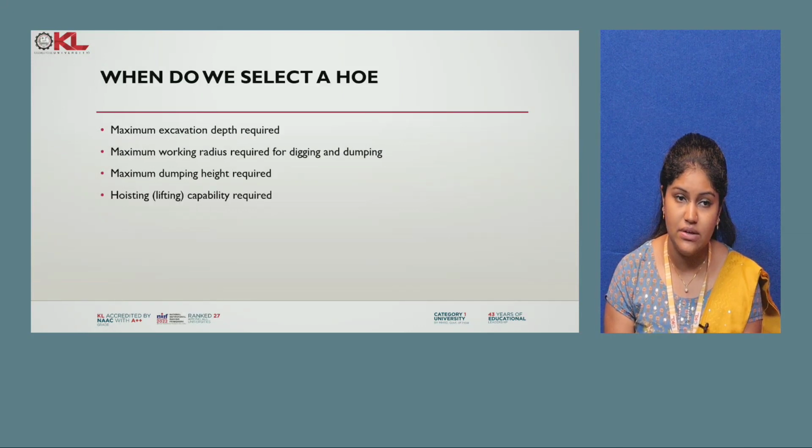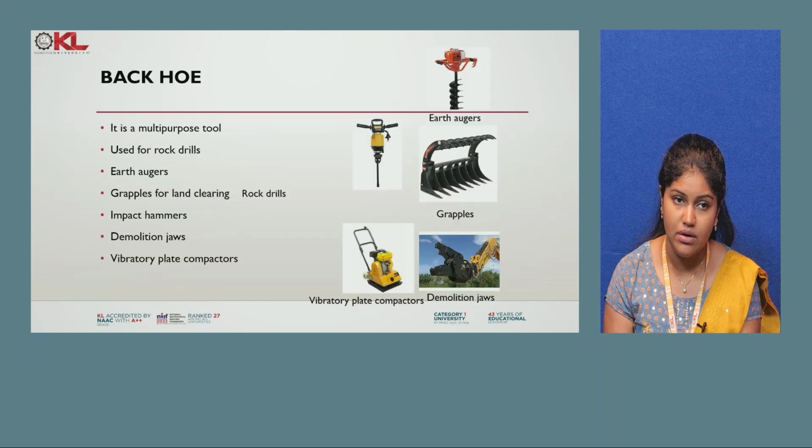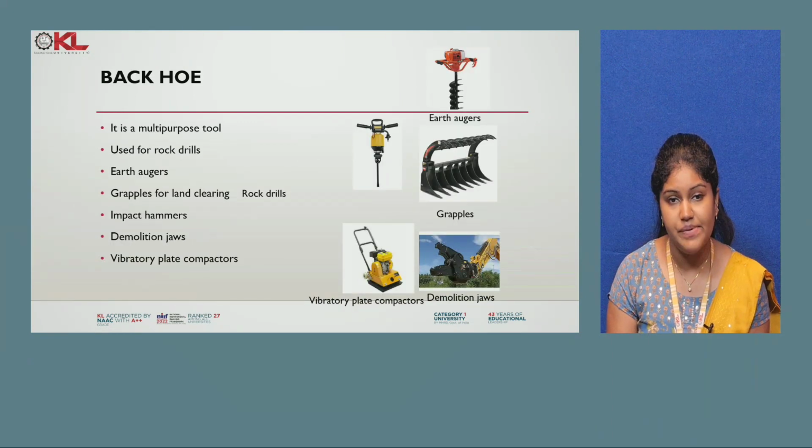When do we select a hoe? When maximum excavation depth is required, or maximum working radius is required for digging, maximum dumping height, or hoisting capability. For this purpose we will be selecting a hoe. So this is the backhoe.